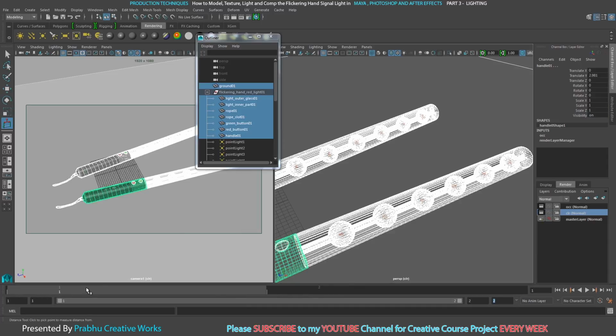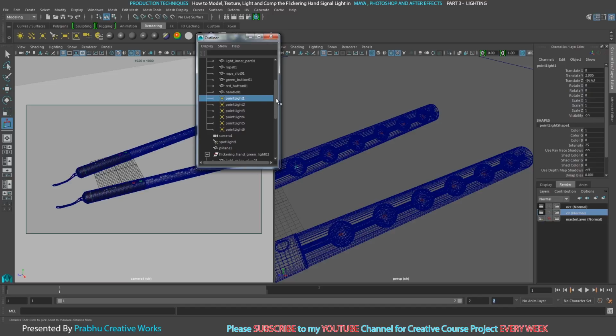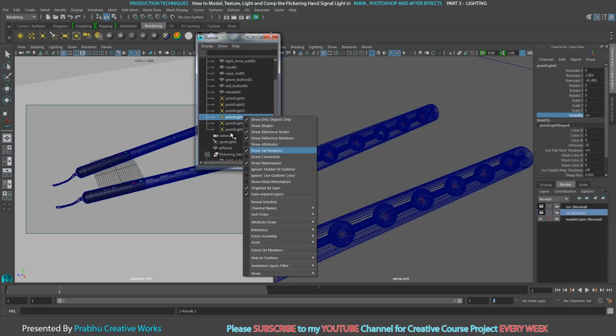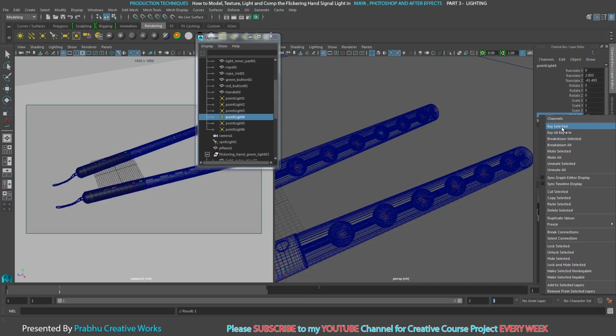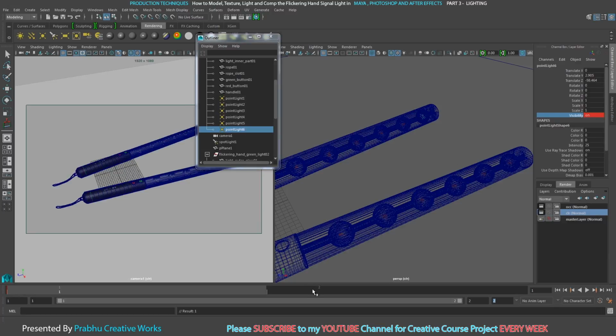So in the first frame I want only the red point light enabled. So go to the red point light. Select the point light, go to channel box and layer editor, right click on visibility and choose key selected. So that means it's on. So you want to do all the other point lights on in the first frame. For our red light, right click and choose key selected. So you want to do this for all 6 lights. So now I go to the second frame.